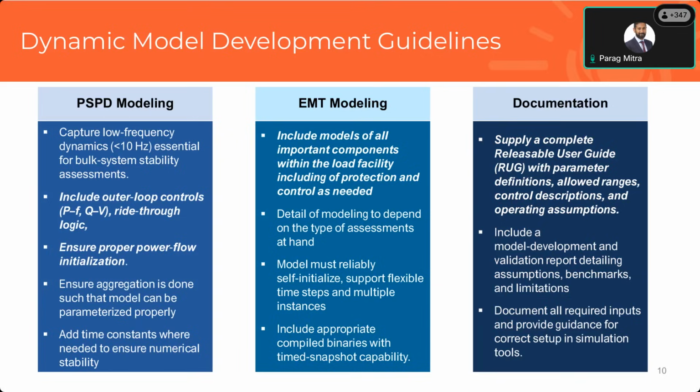We have done this for IBRs in the past, where for weak grid cases, we know that when PLLs are not stable, we want to switch over to EMT modeling to get some sense of what the dynamics look like. But bearing in mind, when we're doing these positive sequence phasor domain models, it is important to include the outer loop controls, the active power frequency, the reactive power voltage, the ride-through logic, etc. We need to make sure that the power flow models are initialized properly.